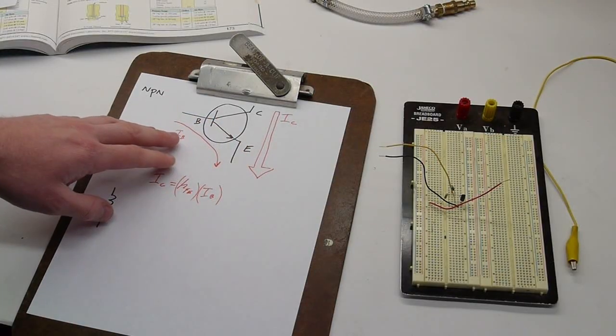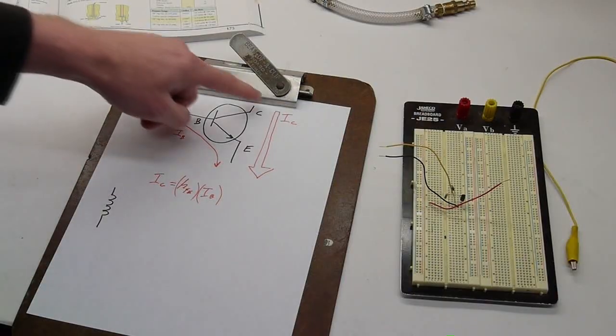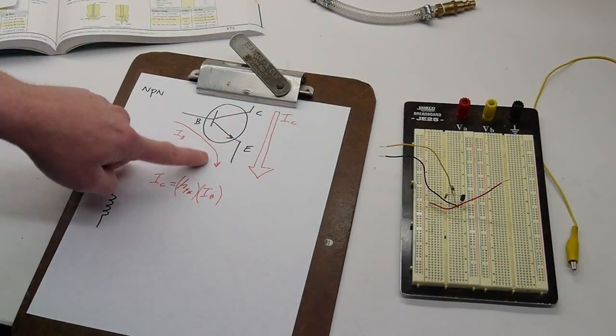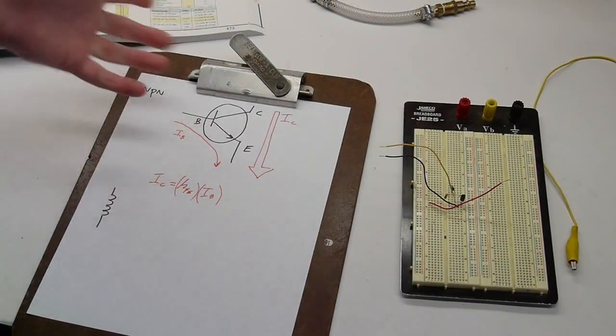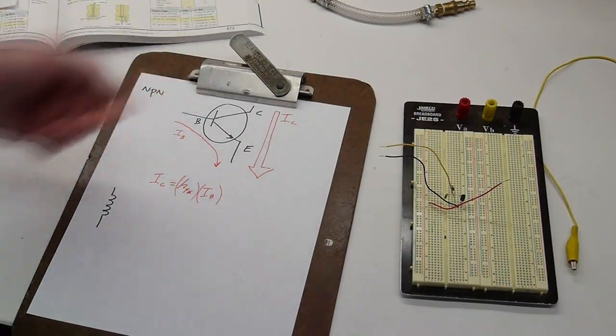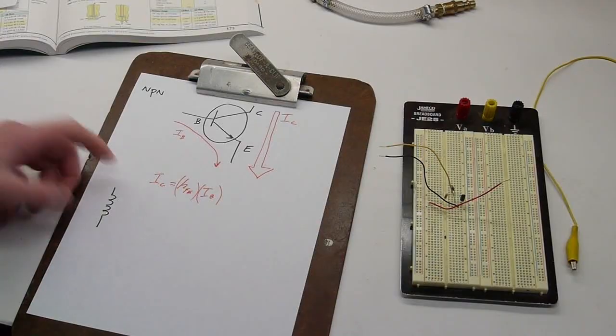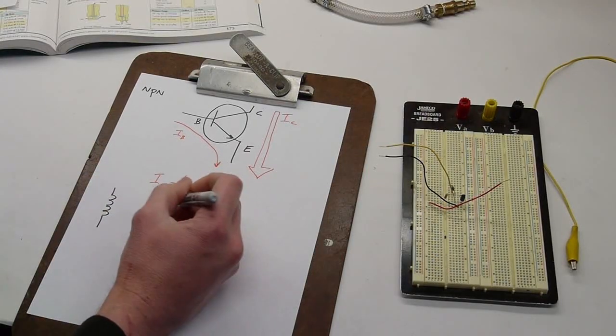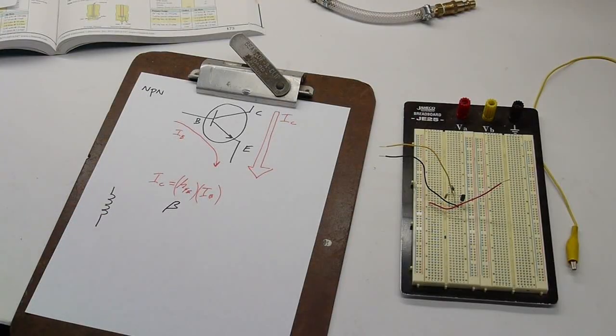So a transistor with a high amount of gain will allow a large collector current to flow with just a small base current, and a transistor with not much gain will not have as much amplification. And that amplification factor is known as HFE, or it's also sometimes called beta. That's the gain of the transistor at DC. I should also point out that we're not talking about AC circuitry here at all. This is all just steady state DC analysis to make our lives easy.